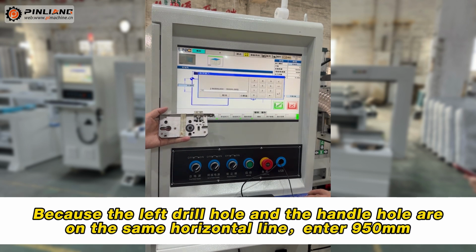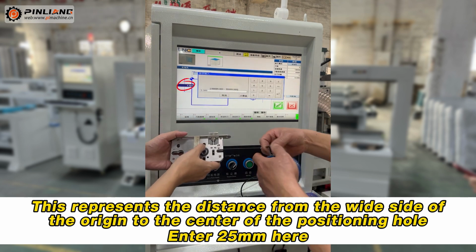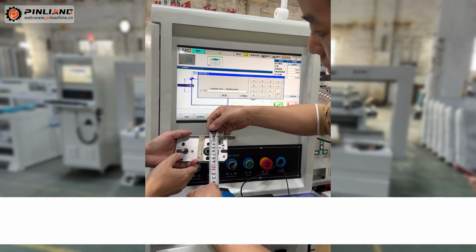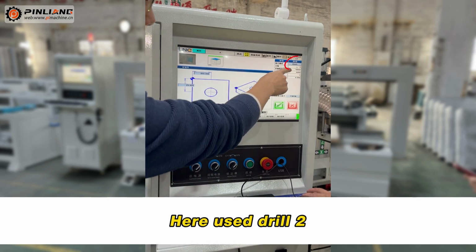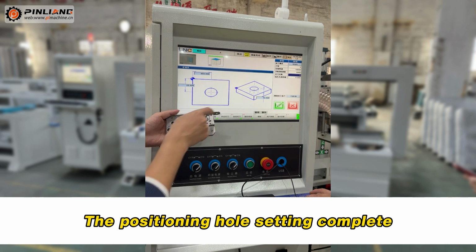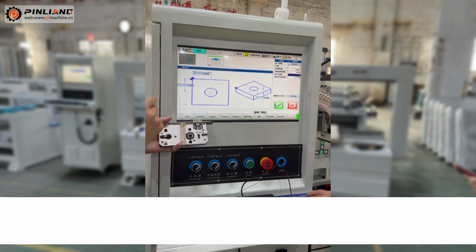Because the left drill hole and the handle hole are on the same horizontal line, this represents the distance from the wide side of the origin to the center of the positioning hole. Here it is still the same 42.5 mm. Here use the drill 2. Just select 3 times of drilling. The positioning hole setting is complete. The rest of the positioning holes can be set according to the previous method.